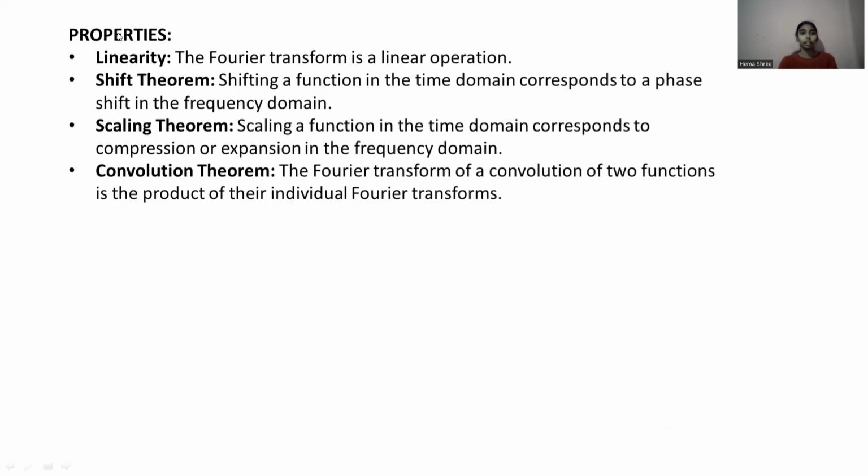Properties. Linearity. The Fourier transform is a linear operation. Shift theorem. Shifting a function in the time domain corresponds to a phase shift in the frequency domain. Scaling theorem. Scaling a function in the time domain corresponds to compression or expansion in the frequency domain. Convolution theorem. The Fourier transform of a convolution of two functions is the product of their individual Fourier transforms.